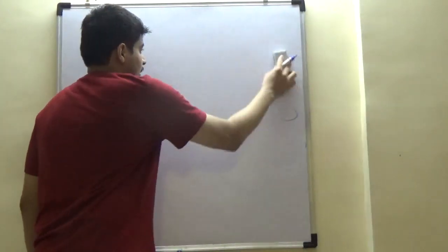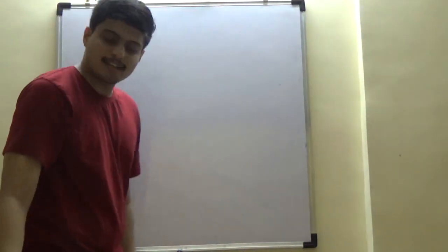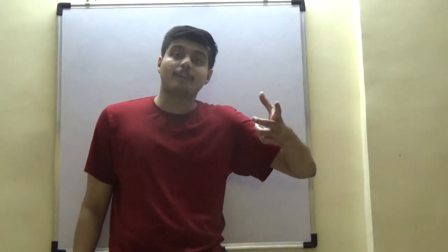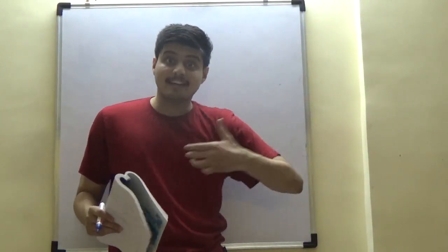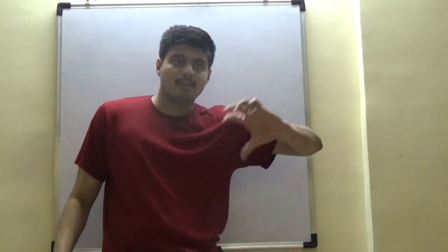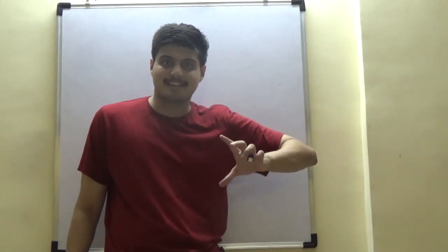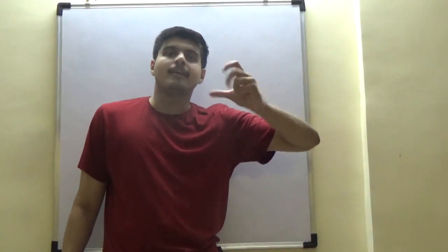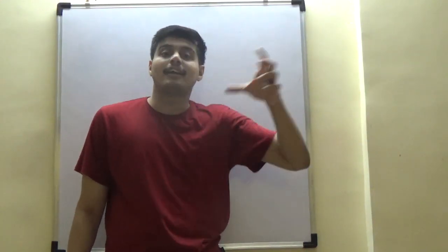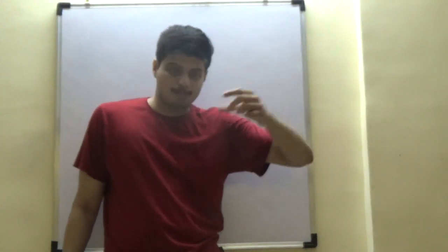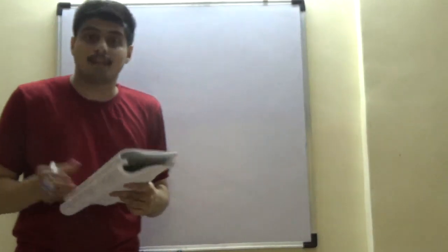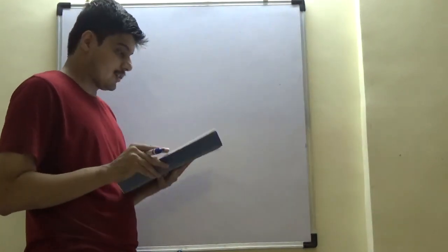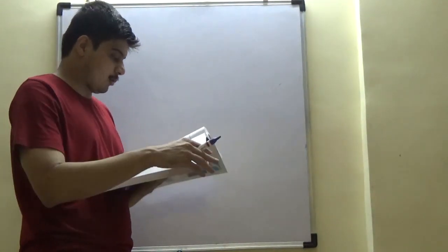which because of bonding is not allowed. So in bonded composites, stress cannot be continuous because of different material property, and in fact to hold them together, this glue is getting that additional stress. So the glue, or the weld, is getting stressed with that difference of shear stress between SS and aluminium. If SS has lower stress because of higher G and aluminium has more, that delta is balanced by the bond that keeps them together. Another insight. Right? So this is the GATE problem that we looked at.